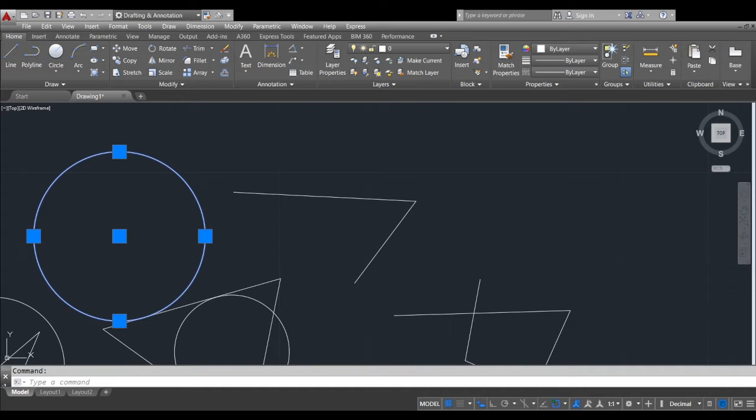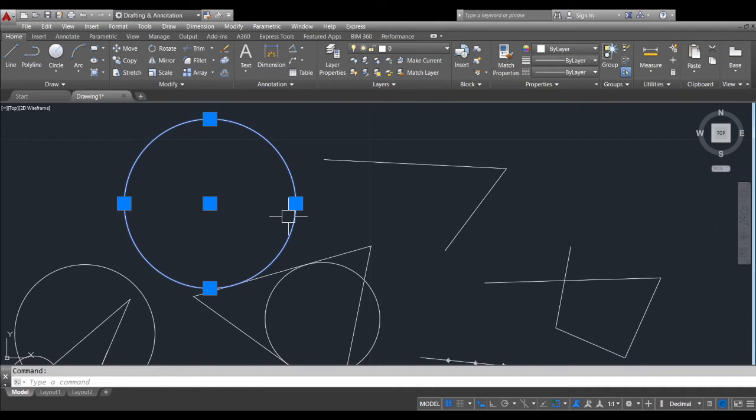And now, our fourth command is the move command. What is move? Of course, we are just going to move things. Let's move it. Okay, so let's move this circle. When we move an object or objects, we can select the object first before typing the command, which means that this specific object has been selected for the command. So for example, let's type move or M. Letter M, move. And then, there is something being asked of us.